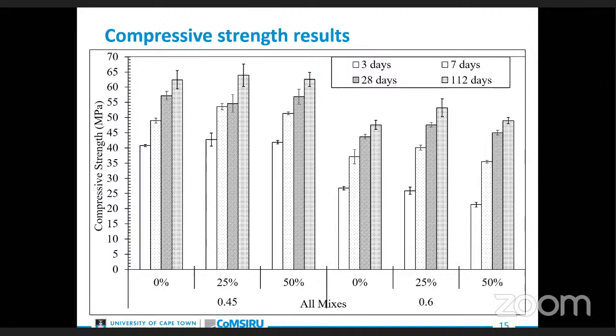Part of my analysis also suggests that the gradual increase that I get in strength in the lower water binder ratio could be contributed to the adhered cement providing extra calcium silicate hydrate to the matrix, while the higher increase of strength in the higher water binder ratio could be due to the secondary reaction caused by the extra water stored in the material facilitating internal curing. Now, it is also observed that concrete mixes increase gradually in strength compared to recycled aggregate mixes.